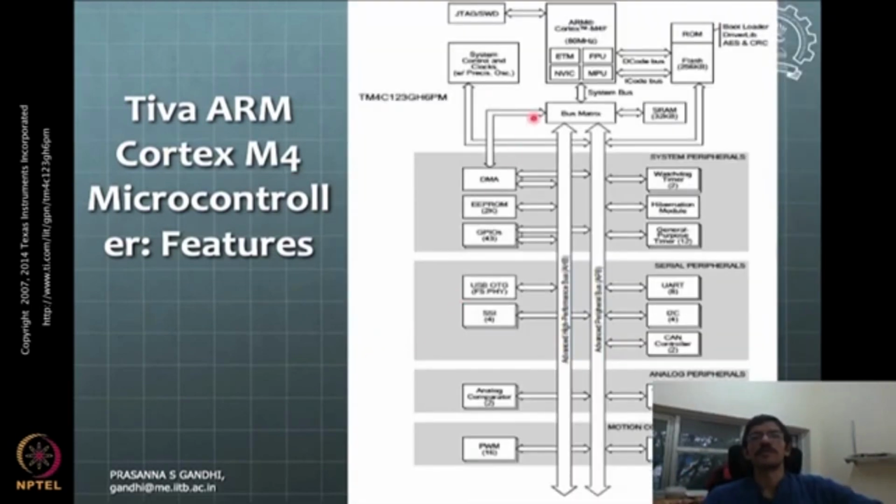This is more detail about the diagram. This JTAG refers to a communication interface which is typically used for downloading the compiled C-level program to the microcontroller memory, and exchanging variables from the memory to the software in which you'll write the code, which in this case will be Code Composer Studio. So there will be some interface that is needed, which will share memory locations to know in real time what is happening to different registers and different variables you have used in the program. They all will be exchanged through this interface to your computer system.